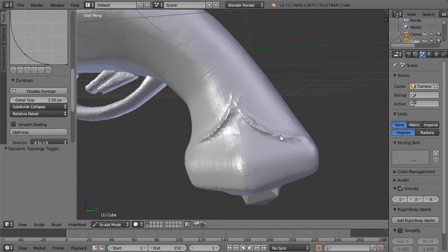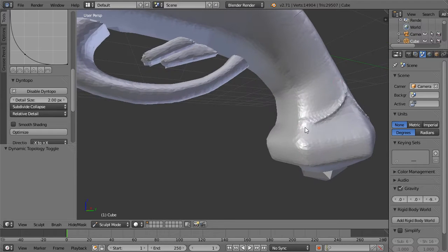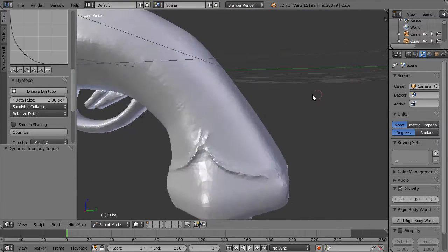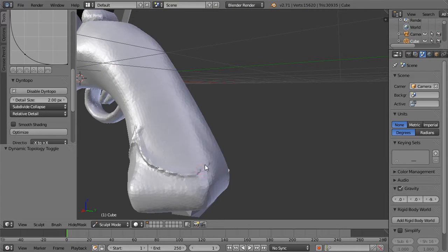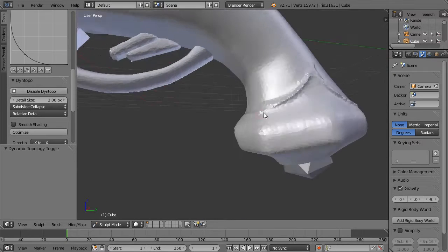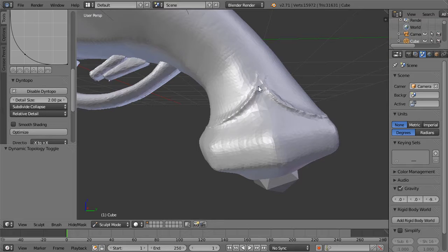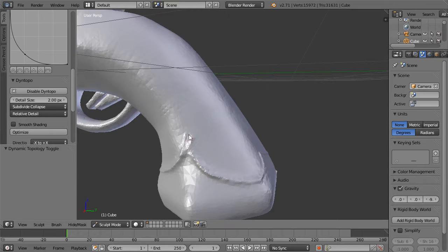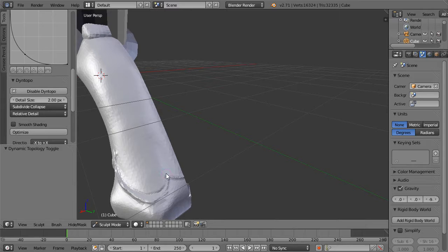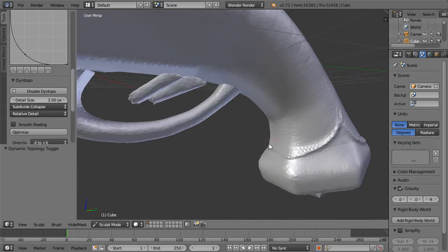All right, just gonna create this, and I'm gonna make sure that it goes around to this side, and same back here. I'm actually gonna add a little flange back here as well. Okay, now we have a little bit of ornamentation. I want to start smoothing it out. So smoothing does not actually affect Dynatopo, while a lot of other ones do. I'm just gonna add a little crease up here because I want to accentuate the difference between these two shapes.